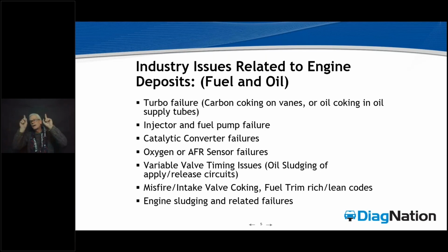Think about it. Higher compression engines in all cases with GDI. If you've got higher compression, those rings are having a tougher time, the light tension rings having a tougher time staying healthy and alive, even more so than in a multi-port car. And ring control was a big problem in multi-port cars, as we well remember. So it's not just about fuel carbons and valve deposits here, okay? The start and the rapid buildup of those valve deposits often occurs because of a loss of oil control on the piston rings. So we're going to key in on that too.